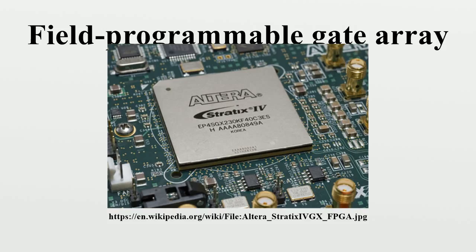to be wired together. Like many logic gates that can be interwired in different configurations, logic blocks can be configured to perform complex combinational functions, or merely simple logic gates like an XOR. In most FPGAs, logic blocks also include memory elements, which may be simple flip-flops or more complete blocks of memory.